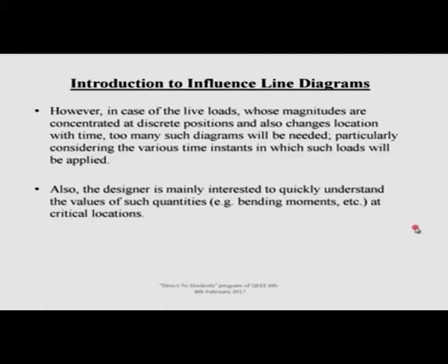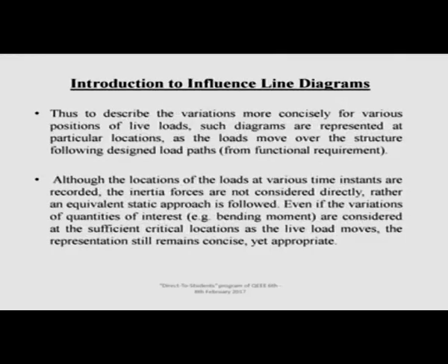So, he is exploring what the variation is in different places, but if the structural form is known to him, he may actually know where these variations become critical, and he will be interested to see the variation of the live load there. Probably his interest is to see, if the load changes positions, how the bending moment and shear force vary at particular locations. To describe the variation more concisely for various positions of live loads, such diagrams are represented at particular locations as the loads move over the structure following designated load paths from functional requirement.